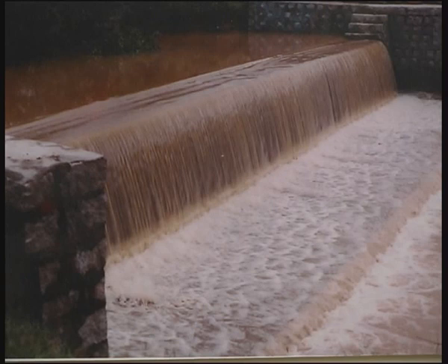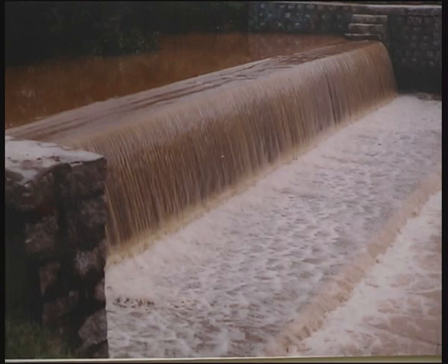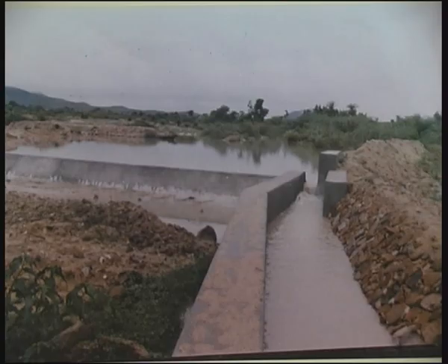One is for the purpose of impounding storages of small quantities and using that storage for irrigation purposes by taking canals on either side of the check dam. In such a case, it is usually called an anicut structure. These anicut structures primarily are intended for diverting the base flows of the streams through gravity flow irrigation canals on either side.